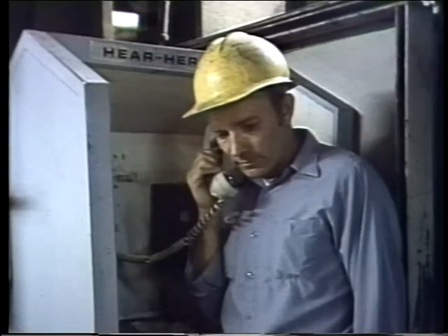In order to find anything wrong, you'll have to watch as the soot blower is operated. And when you do this, certain precautions are necessary to make sure of your safety. Keep your distance. For starters, these things operate under high pressure and often very high temperatures. Eye protection, hearing protection, and breathing protection may be necessary in some of these areas. And be sure to maintain good communication with operations people and your coworkers to make sure everyone knows what's going on.